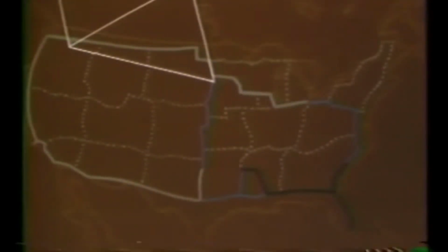Scale control is achieved by a calibration of one side of the Earth-based triangle through a connecting densification network and by comparison with the Coast and Geodetic Survey's high-precision transcontinental geodetic traverse, surveyed with an accuracy of 1 part per million by use of geodometers.